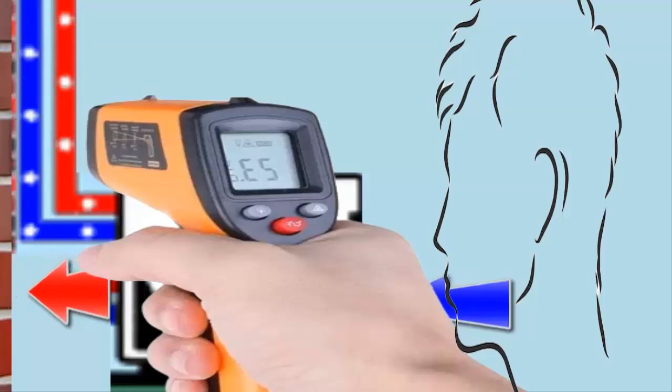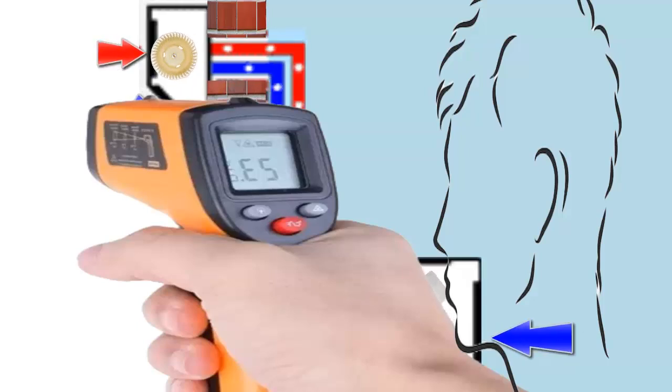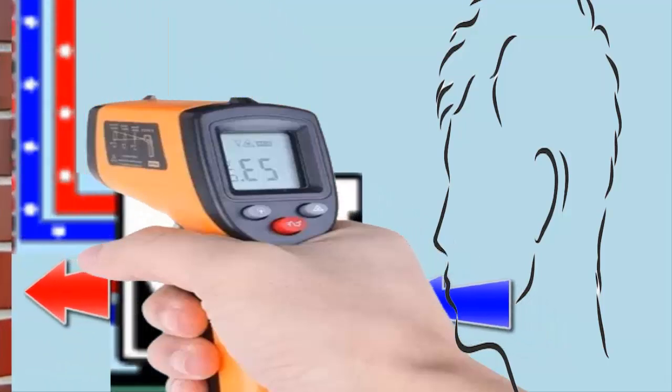10. With a precision refrigeration thermometer, you can check the temperature difference between the thin and thicker pipes. Usually, a very high difference between them is linked to a very high superheat value, generally linked to a lack of refrigerant gas. Consider a high superheat, a temperature difference between pipes greater than 10 degrees Celsius.